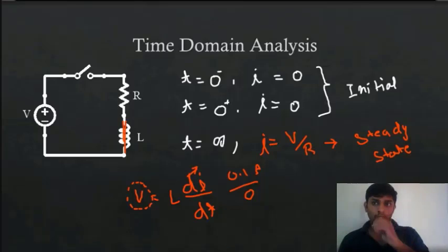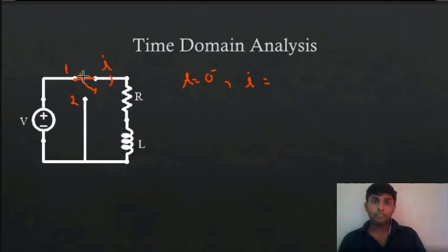So this was the condition that at t equal to infinite, the current was V by R. And in this circuit, what I'm saying is that it was in the stable state before switching. If it was in the steady state condition, then what will be the current at the steady state of the circuit? I'm just asking the value of this I.